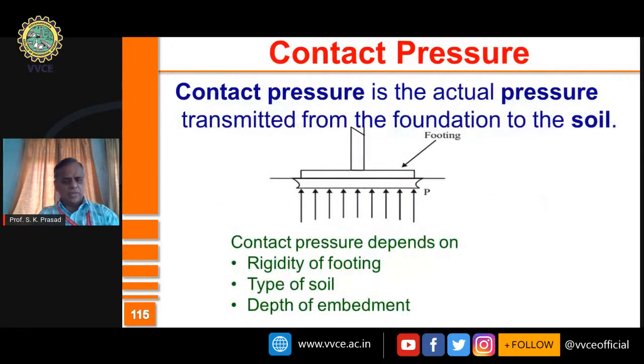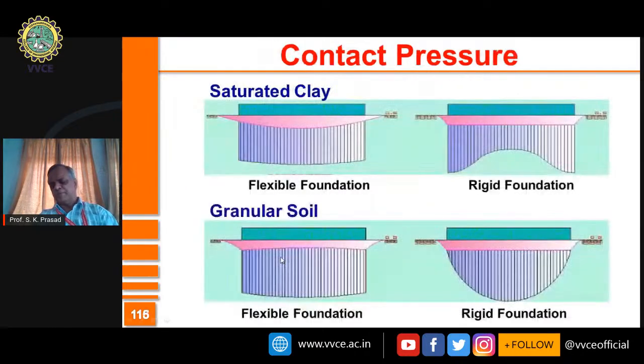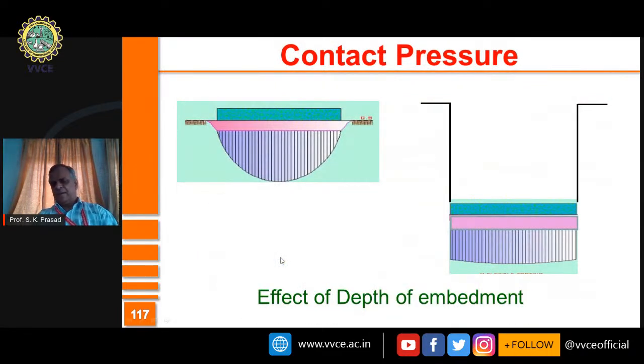You should also know that contact pressure depends upon the depth of embedment. At shallower depths, the contact pressure is not generally uniform. On the other hand, at deeper depths, contact pressure will be more or less uniform, whether it is sandy soil or clay soil.